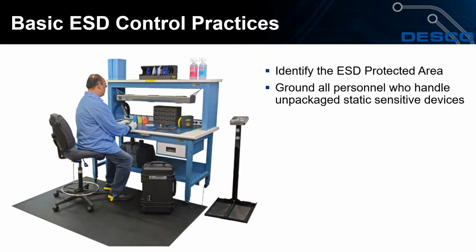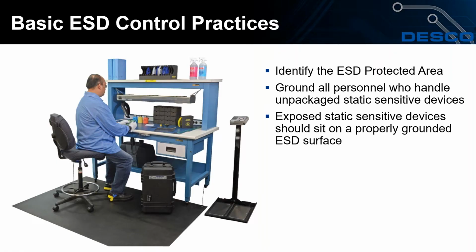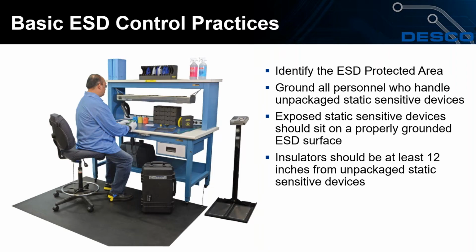The most important thing you can do is ground the human body. So we want to make sure that we're either wearing a wrist strap while we're seated, or wearing ESD footwear on a grounded ESD floor if people are walking around while carrying their ESD sensitive devices. Exposed static sensitive devices are those that are not grounded. If those exposed ESD devices aren't grounded, they either need to be sitting on a grounded work surface, or we need to keep them in static shielded packaging.